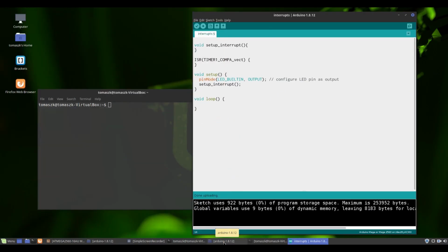What is an interrupt? If you are running a code and there is some signal indicating an event that requires immediate handling, the microcontroller pauses the code and gives control to a special interrupt handler function. After this function is completed, the code is resumed. The interrupt signal may come from outside of the system using a microcontroller pin, or from the inside.